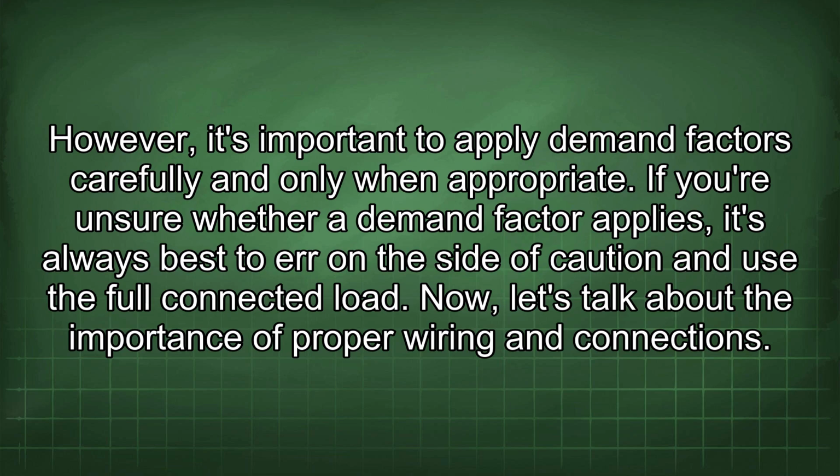However, it's important to apply demand factors carefully and only when appropriate. If you're unsure whether a demand factor applies, it's always best to err on the side of caution and use the full connected load.